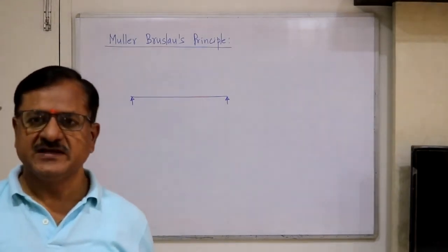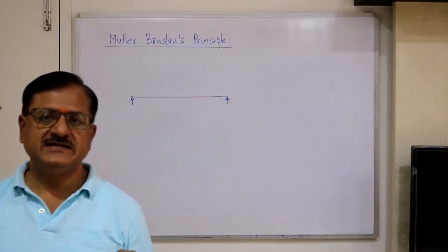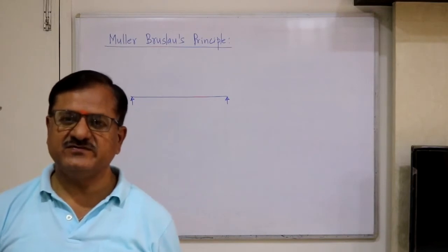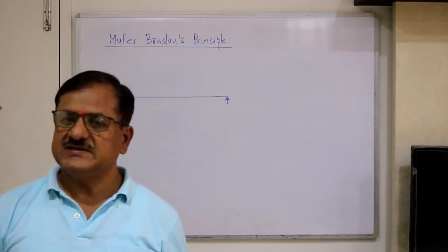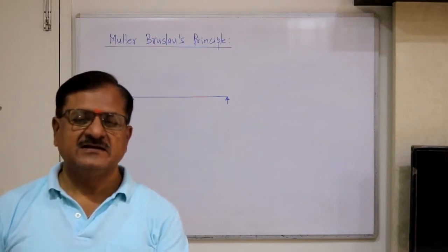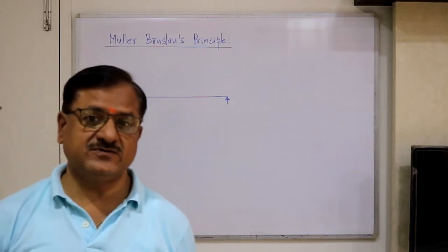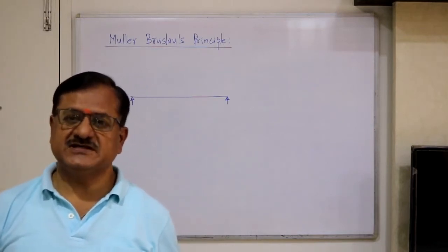That's all. It means introduce a unit displacement in the direction of the structural function for which the ILD is to be plotted, then, without disturbing compatibility, by maintaining the continuity of the structure, the deflected shape of the structure